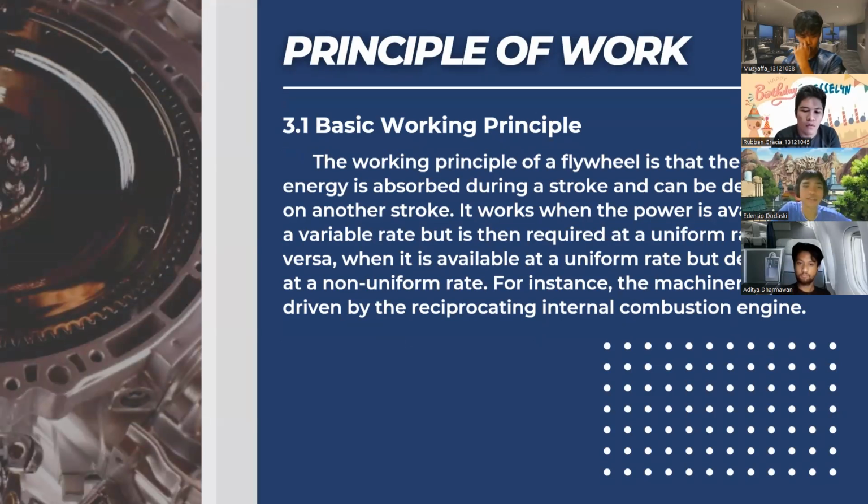The basic working principle of a flywheel is quite interesting as it stores energy for the vehicle's usage. Flywheels save the power in the form of kinetic energy. The kinetic energy is absorbed during one stroke and then delivered on another stroke. It works when the power is available at a variable rate but is required at a uniform rate, and vice versa, when it is available at a uniform rate but demanded at a non-uniform rate. For instance, machinery driven by a reciprocating internal combustion engine.